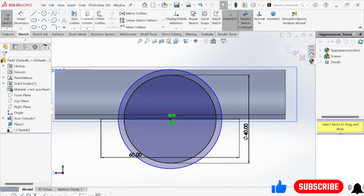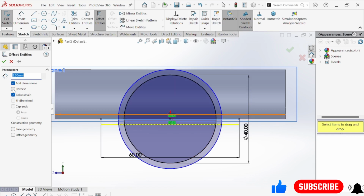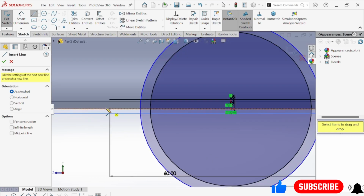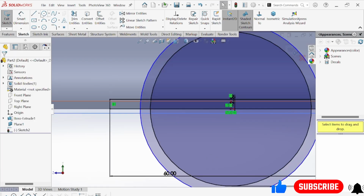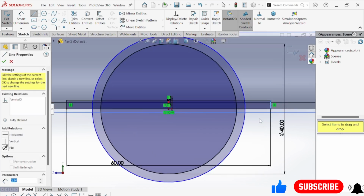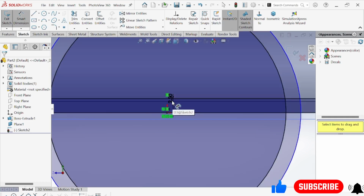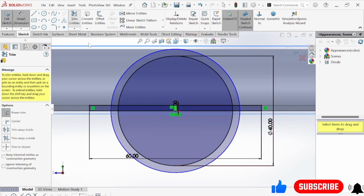Go to the normal tool, again go to offset, select this one and reverse direction, and also make this one okay. Now simply close this one, repeat the process again. It's a very simple part, no need to worry about it. You can also practice this thing on your own. Now come here, make this one 2. Yeah, now here you see it absolutely looks fine.